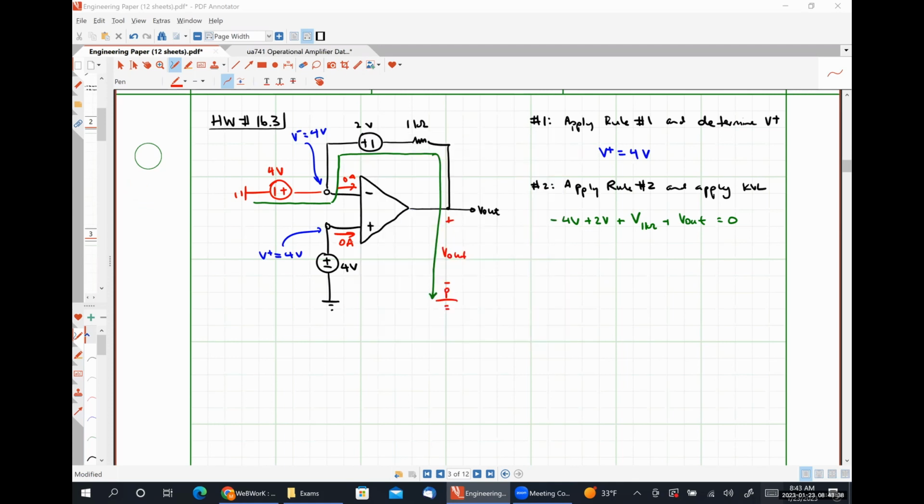So I see 0 from Levi and -2 milliamps from John. So Levi is actually correct, right? The reason why I say that: if there's no amps flowing here, this must also be 0 amps, right? Which in turn means this is 0 amps. The 4 volt source that I have directed out to the left, like I said, isn't actually there, right?